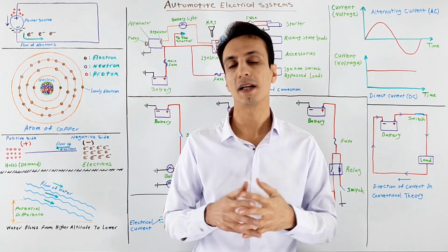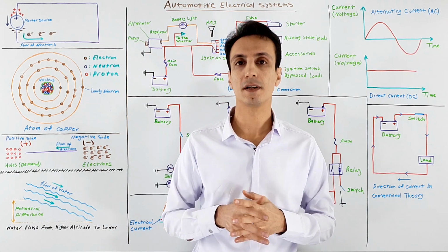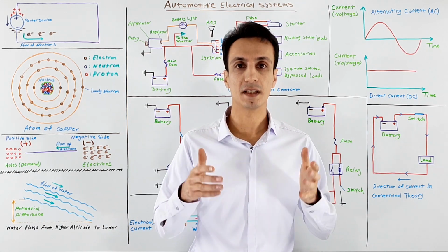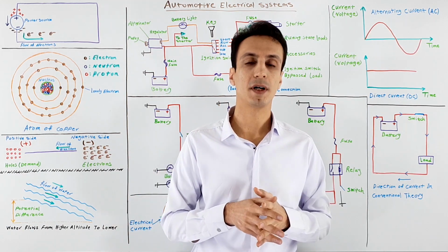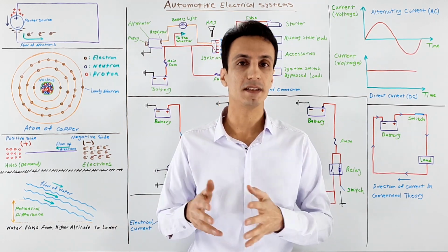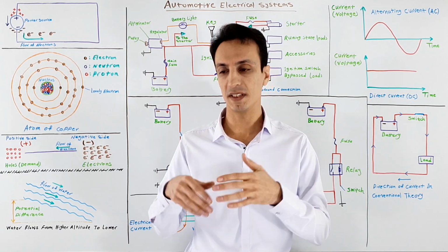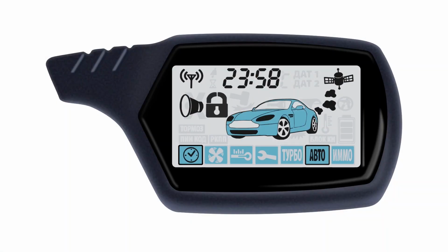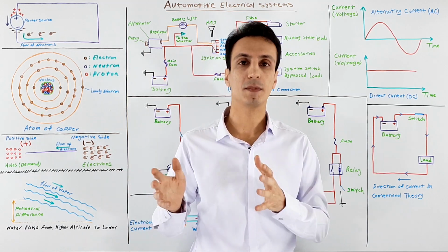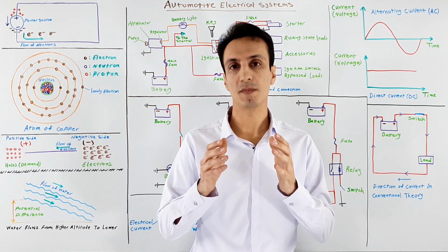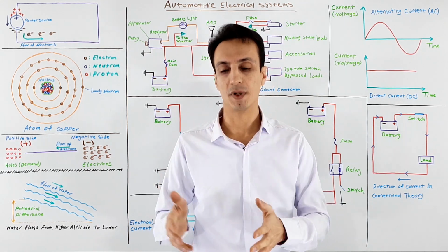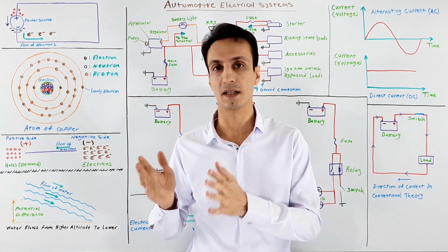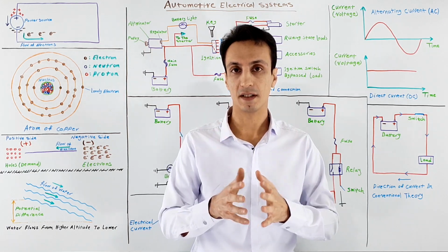When the car is off and even the key is out of the car, the battery voltage is present and can be used. Some systems and components use this electrical power when the car is off and is resting in parking state. One of these systems is the security system that is vigilant for any intrusion, and also the engine control module, like many other modules, is receiving constant battery voltage to retain some data in memory and also perform some leakage tests and calibrations even when the car is off.